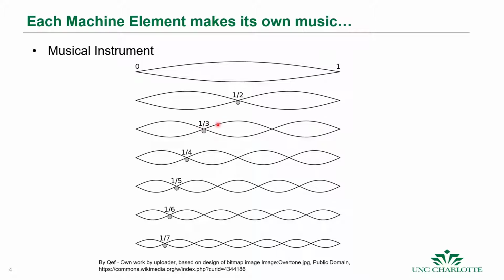So if you're measuring vibrations, where you place the sensor can really matter. Sometimes you just need to move it around and try to find where you feel the most vibration. And obviously, if you wanted to get the greatest sensitivity, you'd put it at the peak of a mode shape. By analogy, this is kind of where we have lived for the natural frequency, but continuous structures can have higher order mode shapes as well, as seen just here in the example for a musical instrument.